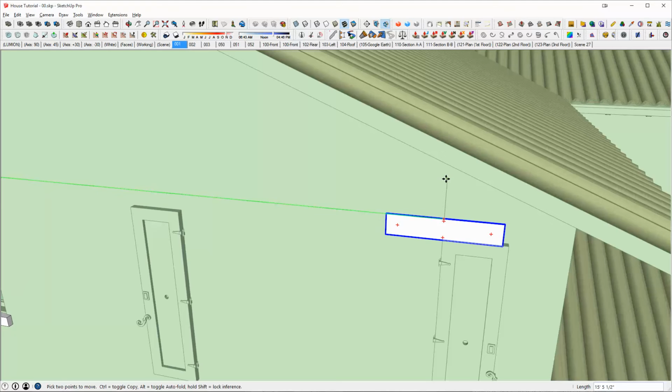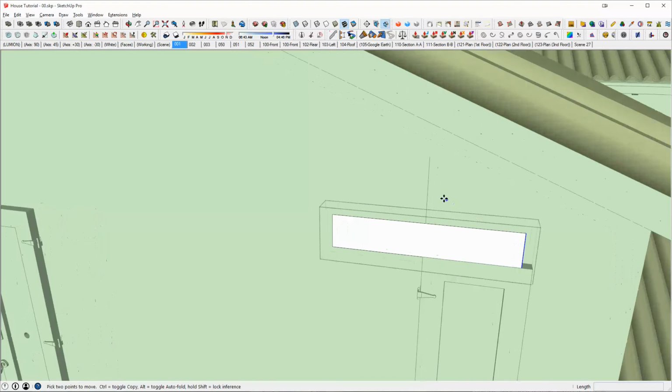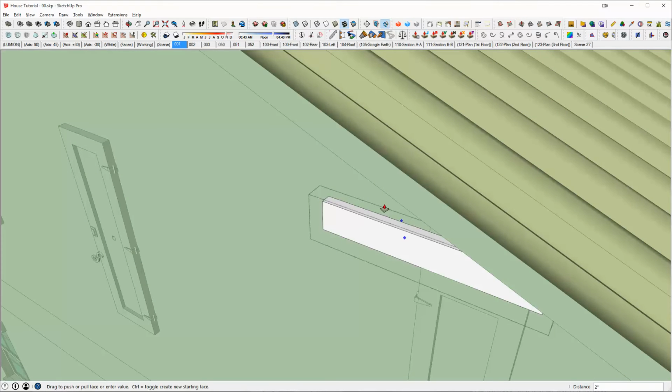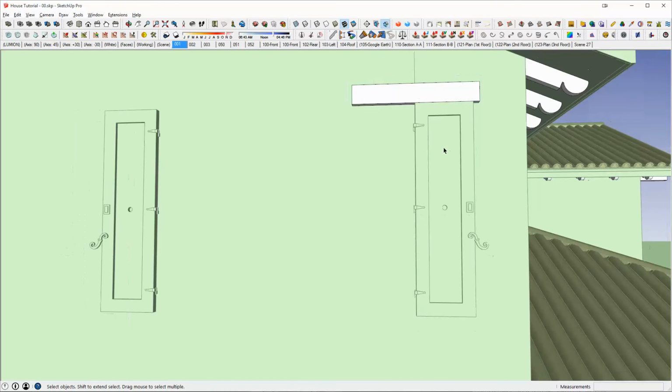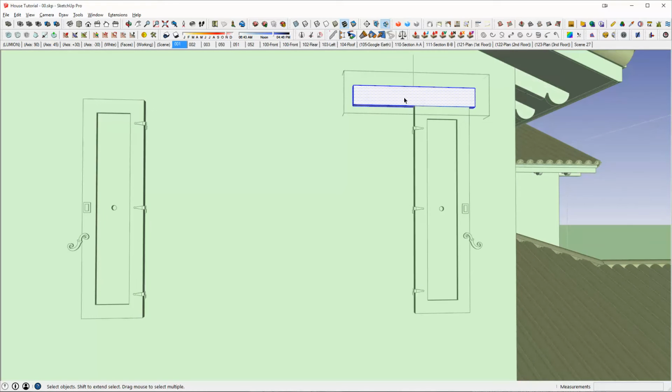So the important part really is we need 3 feet plus 4 inches. So we'll add an additional 3.5, 5.5, 7.5 inches, and that should give us our 3'4". And we'll slide this guy back right over here and slide there. There we go. And so that's our head trim, that's going to be for our faux shutter detail.